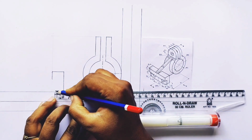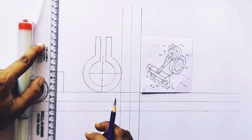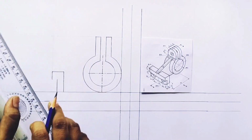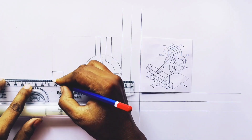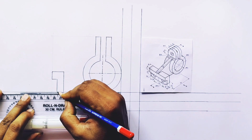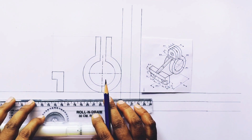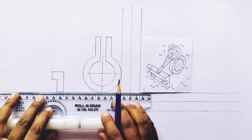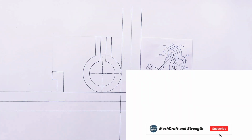So here the thickness is 10, so mark 10 mm, and the height is equal to 20, so up to 20, and draw that one horizontal line, it is 8 mm. Okay, so here the rectangular block front view is complete. Then next, the horizontal line of the rib, so draw that.